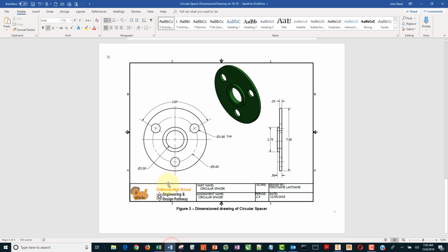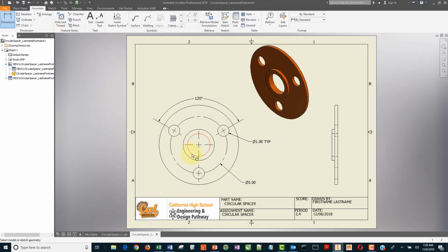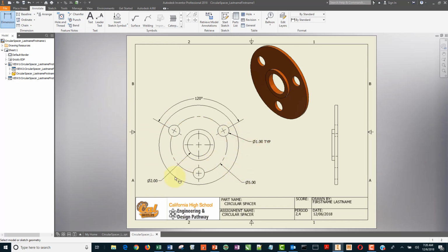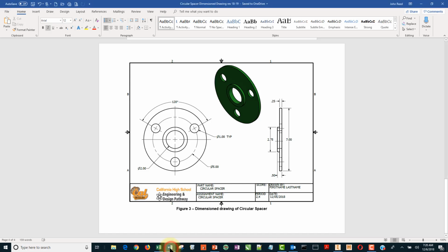And there's one more, which is the center hole here, so the one there. So we can come here and pull out like that. We want those leader lines to be as close to 45 degrees as possible. This one, not quite 45 degrees, but it's adequate. So let's see if that matches what we needed to do there. Not quite. You can see that the lines here extend outward.